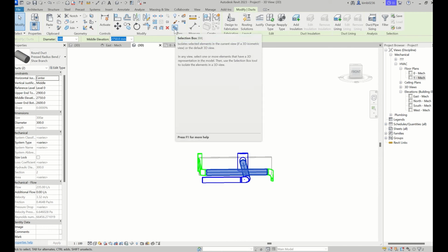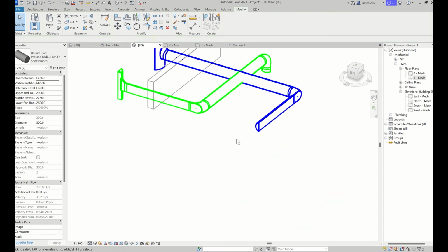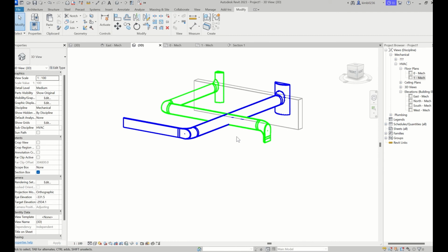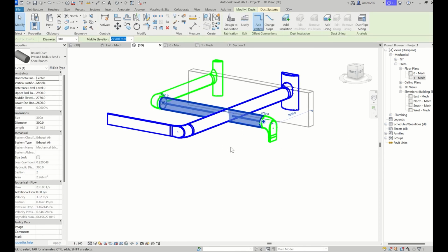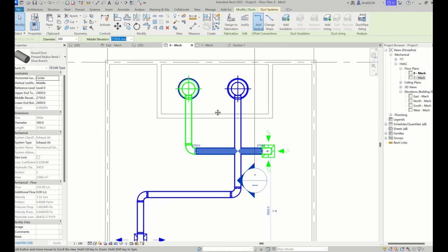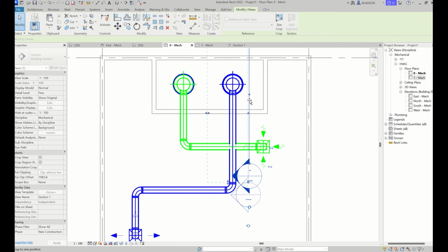So I'm going to use the box tool to check it out. Look, BX, love this little command. And you can see it more clearly here. So let's get one duct out of living inside the other one. My favorite way to do this is to work in a section view so that you can get a good view of it. We've already got one set up here, so let's go ahead and use it.